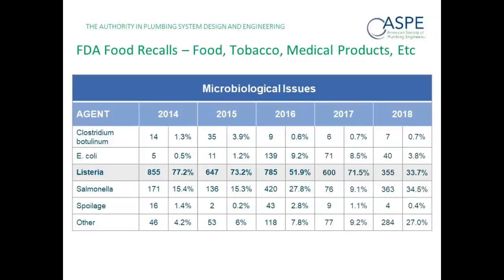Oh, if the plumbing system is sealed, yes. I think what the question is, and I don't know who asked that question, is that there's direct and indirect drainage systems. So if it's hard pipe from, let's say, your sink to your wall, and there's no air gap or air break or anything like that, then I think that's what they're referring to as a direct drainage system, as opposed to an indirect where you would have an air gap in a floor sink and maybe it would be discharging into that.